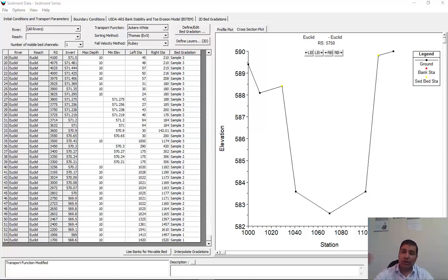Sediment that enters the cross section's control volume leaves the control volume. Capacity for the node is set equal to supply, so the cross section will not deposit or erode. This feature was designed for channel bends, where multi-dimensional channel dynamics keep sediment from depositing, but the one-dimensional transport approach computes deposition.